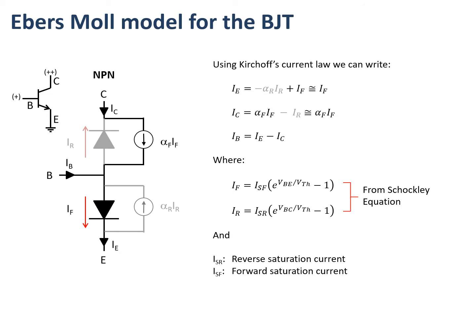So that final third equation there is a very fundamental equation about the bipolar transistor and must always be true. In terms of the diodes that make up the transistor, we already know from basic theory of diodes what those currents will be. They're just related to the barrier in the diode, the thermal voltage, and they relate through these equations known as the Shockley equations, which tell us what the forward and reverse current of the diode would be.